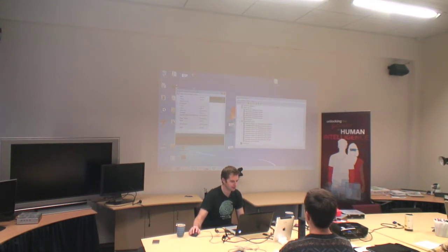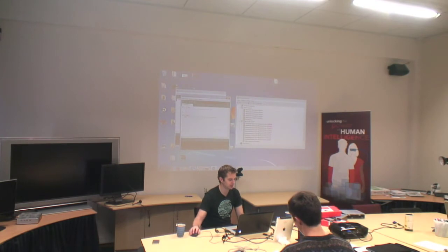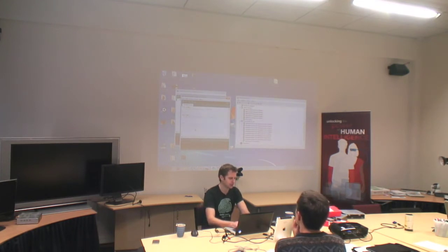But yeah, so if we go into Examples, Basics, and BareMinimum, this is what your Arduino sketch will look like. Obviously, it doesn't have a draw method because there's nothing to draw on because we're running it on hardware. We basically have two functions, one which is setup, which happens when we first turn our Arduino on, when we first plug it in, and one which is loop, which runs as fast as the Arduino can possibly process it. So the setup code gets run once, and then the loop code just runs and runs and runs. You can do all the same things you can do with Processing, so you can create a new function, and then you can call your new function if you so want.